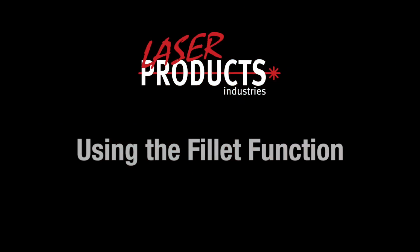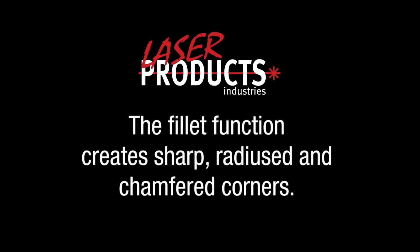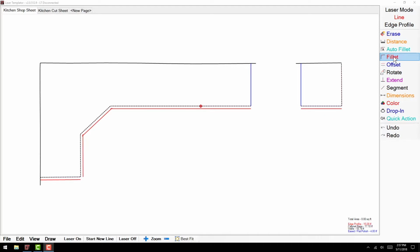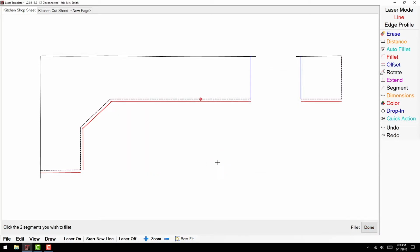In this video, we will show the multiple benefits of using the fillet function. The fillet function creates sharp, radiused, and chamfered corners. Click the fillet button on the right-hand sidebar. Select the type of corner you are designing, from radius, chamfer, or sharp corner. If you select radius or chamfer, you can enter the dimension in inches for these options in the measurements bar above. Click OK. Select the 2 adjacent lines to be filleted, and the fillet corner style will automatically be applied.